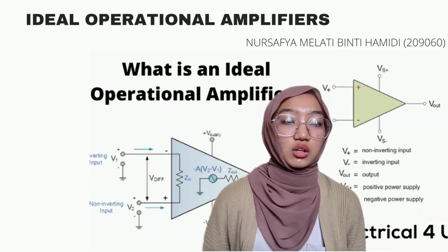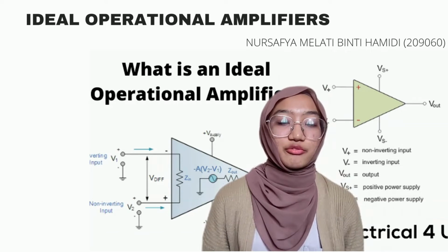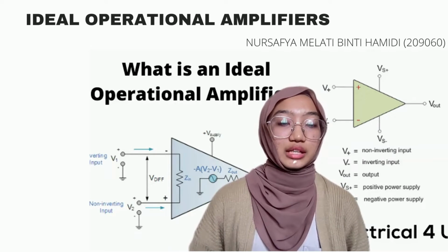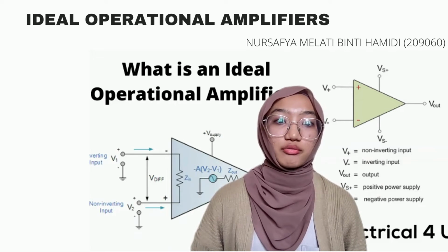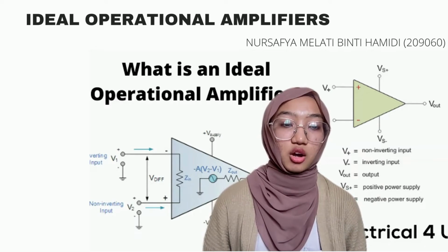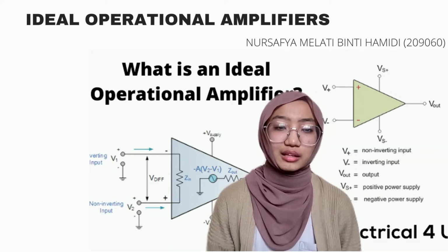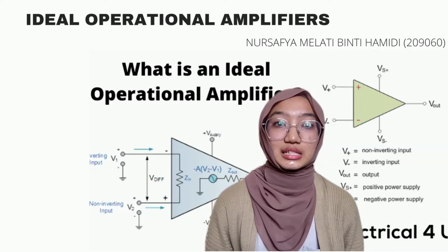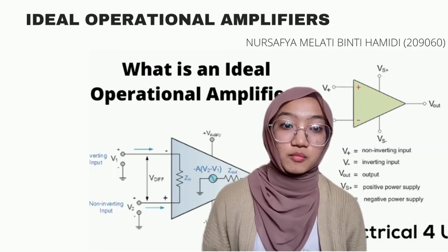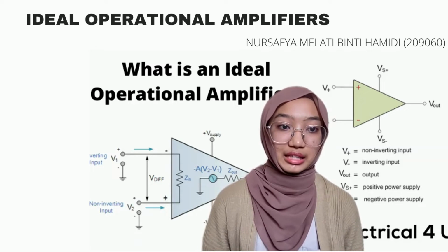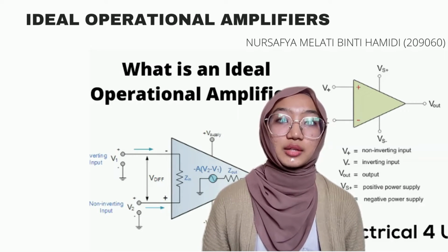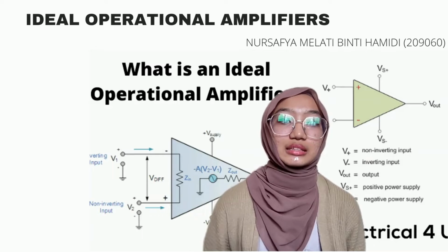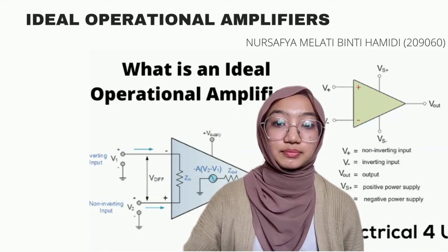Practically, real-world operational amplifiers have finite characteristics, but in most applications are close enough to the ideal to make a huge range of inexpensive, high-performance analog applications possible. Here are the building blocks for analog design. One key to the operational amplifier's design is nodal analysis. Since the input impedance is infinite, the current in and out of the plus sign and the negative sign input nodes defines the circuit's behavior.